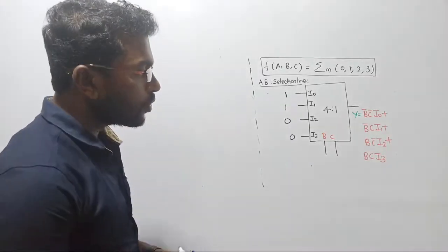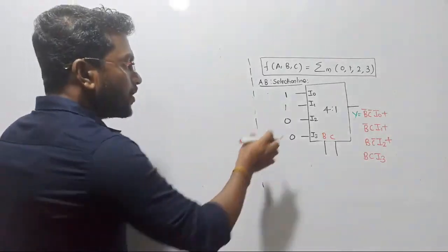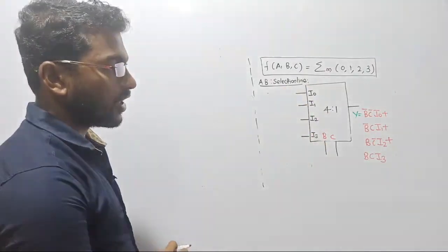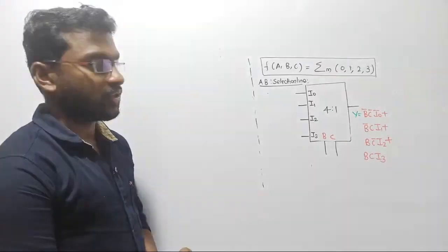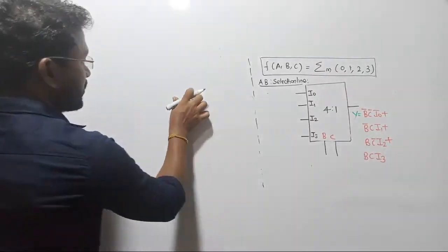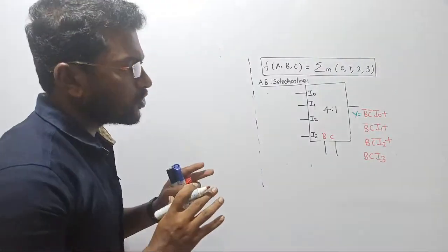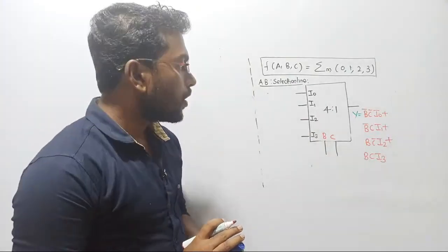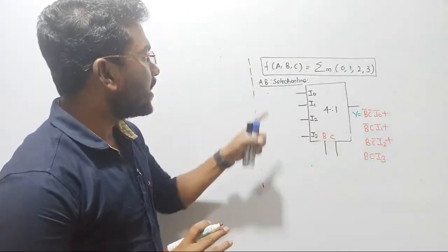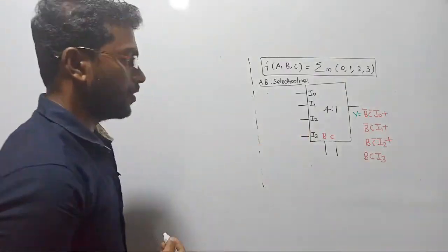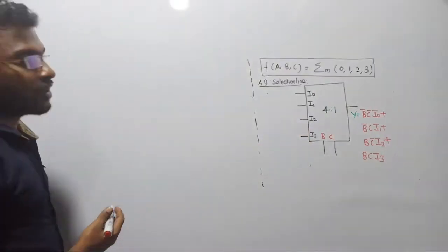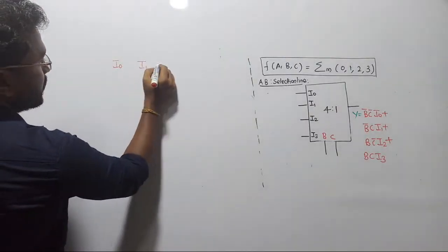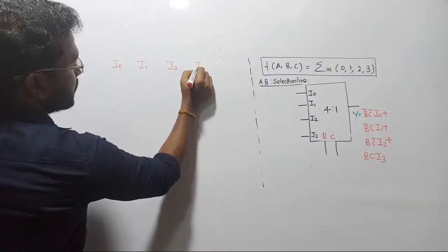Now what I have to do, we have to figure out the circuit. Anyway, the question is number of input lines, right? So input lines is not known. Input line is not known. We have to identify the input lines. Shall we proceed? Yes, let's target. Once again, if you carefully observe these things, B, C are going to act as a data selector. Now which is the input boolean variable? A is going to act as an input boolean variable, right? So let's travel along with the A such that your input variables are I0, we are going to consider I1, I2, and we are going to consider I3.